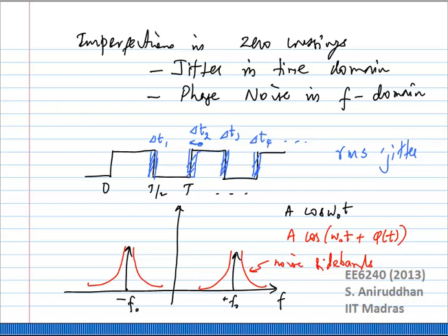In fact, inside the mixer, we discussed this last time, you look upon the LO signal as simply a signum function, right? It just switches the current. And if the sinusoid is large enough, it will completely switch the current, and quite quickly also. So the amplitude itself is not particularly significant in the examples we took, which are switched mixers, whether active or passive mixers. Obviously there are other kinds of mixers where the LO amplitude could be significant, but we did not consider them because they are not very commonly used in IC design.